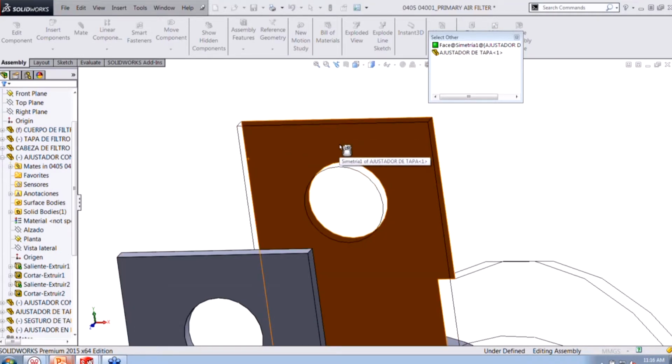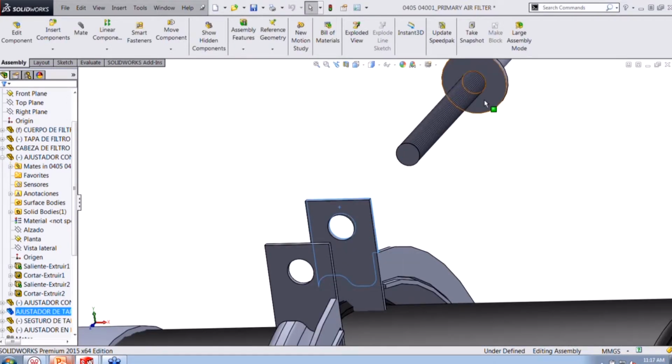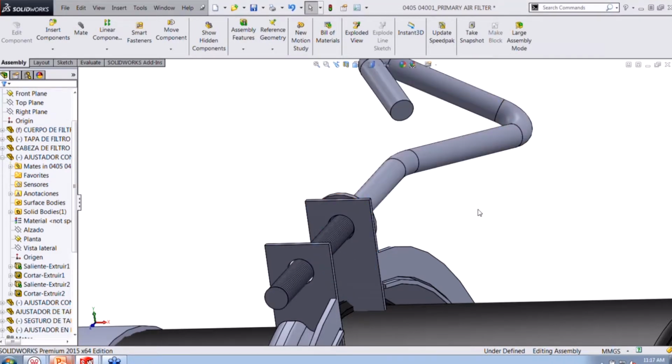Okay. So I'll left-click, notice how it highlights on the other face, and I'll go ahead and Ctrl-select that face and then make those coincident. So that'll be Select Other. It's also available outside in an assembly. You can also use it in parts as well.